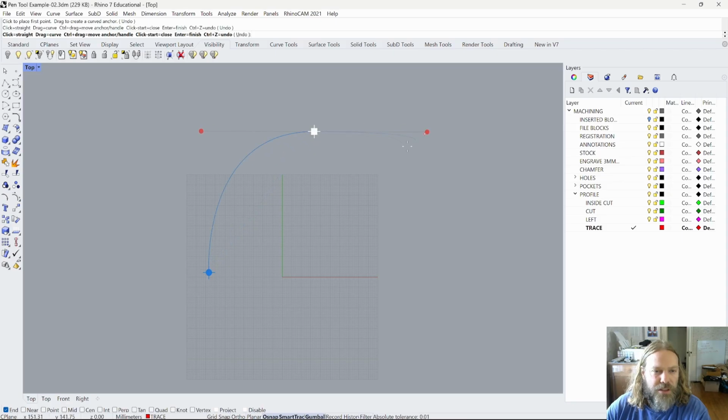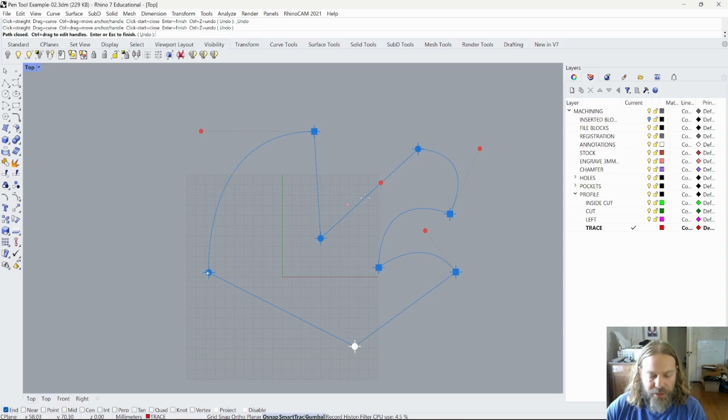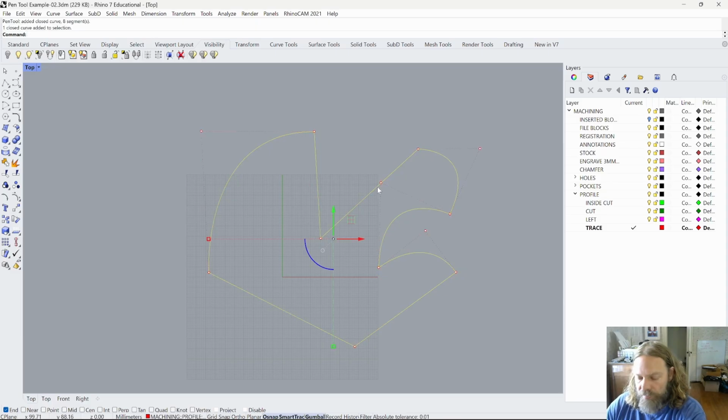To change directions, you can just click on the anchor point and then you can go to straight, or you can click on the anchor point and keep doing curved but change the direction. And if you're familiar with Illustrator, it works just the same. Control Z will take you back, and then you can add additional points if you need to. So those are the basic functionality.